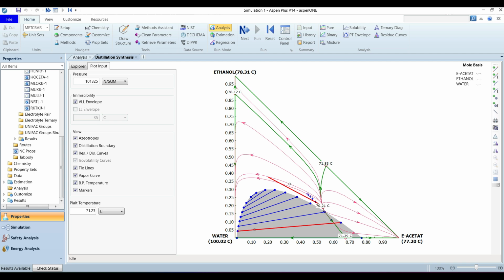But for that purpose, we cannot move off the residue curve. So you can add another residue curve, a random residue curve, take the 3rd option, and just drop it on the product from the liquid-liquid extraction. So here you can add another product. So again, after the first distillation, then liquid-liquid extraction after adding more water, we can have a second distillation process, and for the second distillation you can get the product from the reboiler and the condenser.